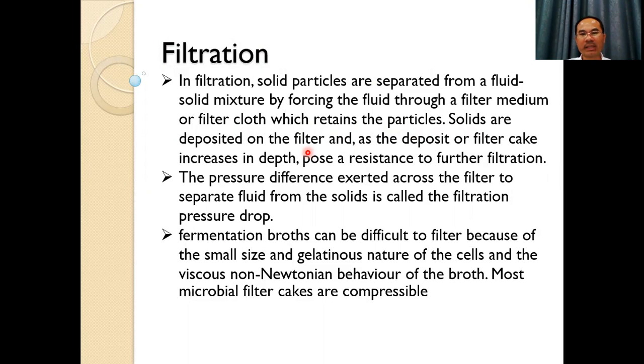The filter cake will increase in depth as we increase the flow of the fluid across the filter. The pressure difference across the filter needed to separate fluid from the solid, for the liquid to pass through the filter while the solid deposits, we call the pressure drop.